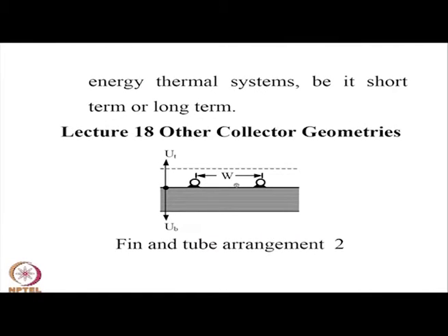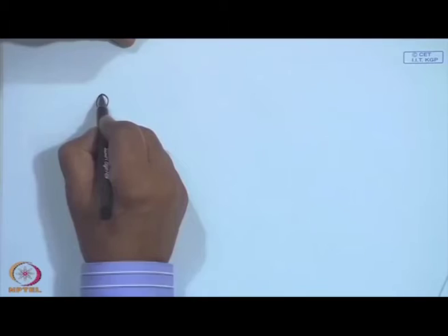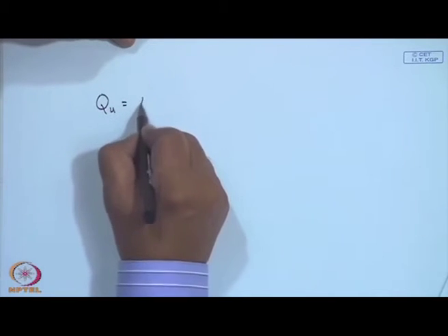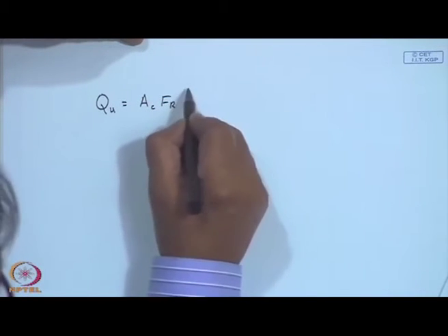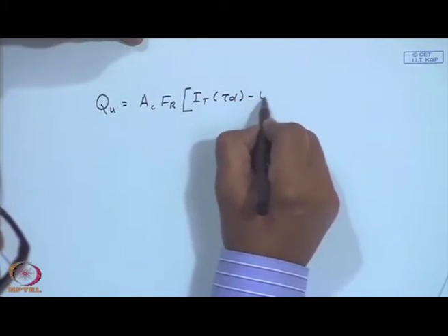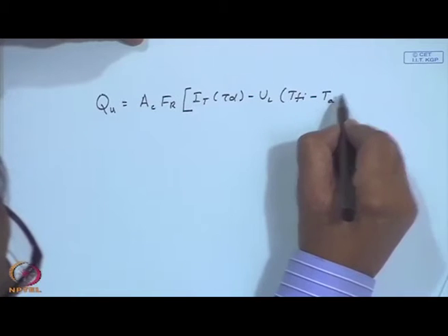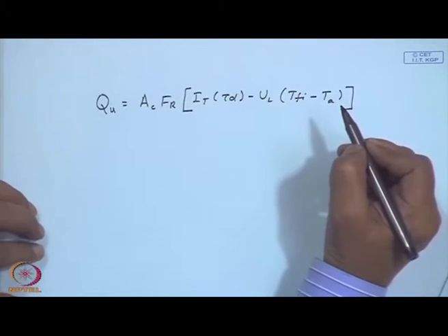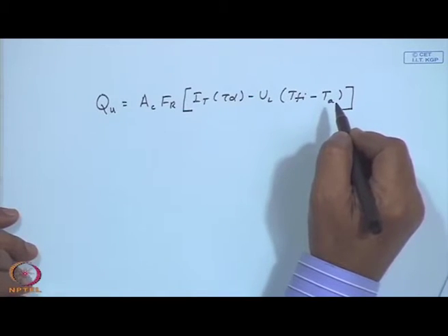Now, this is from this equation, which is basically derived in 1942, Hottel Whillier Bliss equation, though there have been some modifications in terms of F r, F dashed, etc., is the single most commonly used equation in the solar energy literature, and it will be used in the simulations for the collector, applying it over the time period that is required.